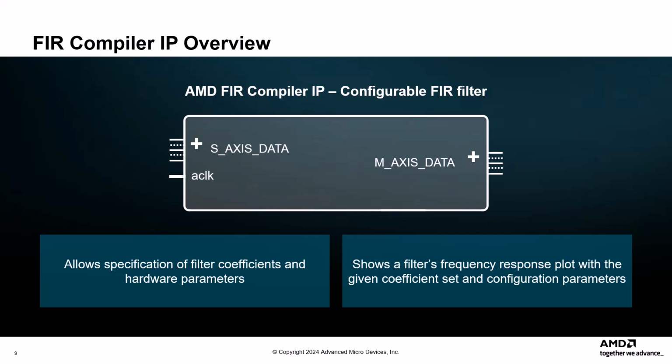In this demo, we'll be testing three FIR filters with different frequency responses, low pass, band pass, and high pass, by using the same chirp signal to show how quickly a DSP design cycle can be implemented in behavioral simulation and validated on the KD240 starter kit.